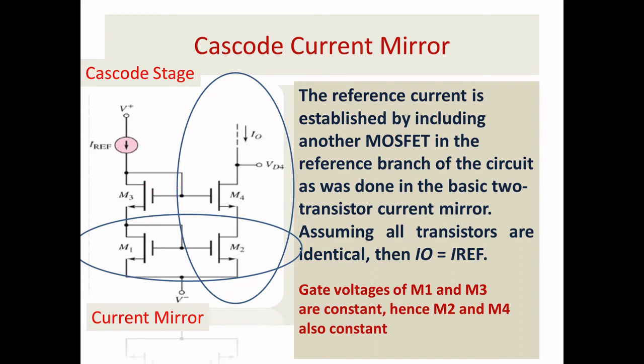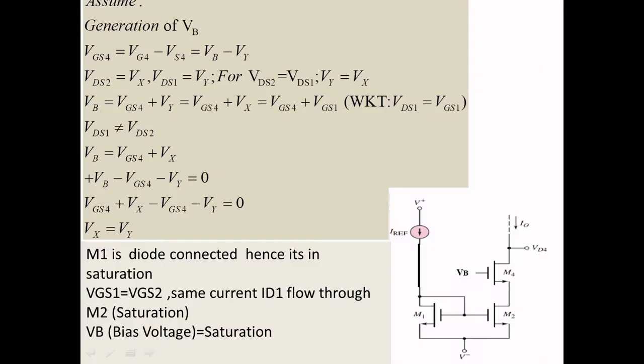So we will begin the concept like this: I will remove this M3, such that I can give some bias voltage. That bias voltage will make the changes with respect to I naught suppressed. So we will see that now. See, I have removed the M3 transistor and placed only M4. This is a cascoded connection with the M2. So I am giving some bias voltage.